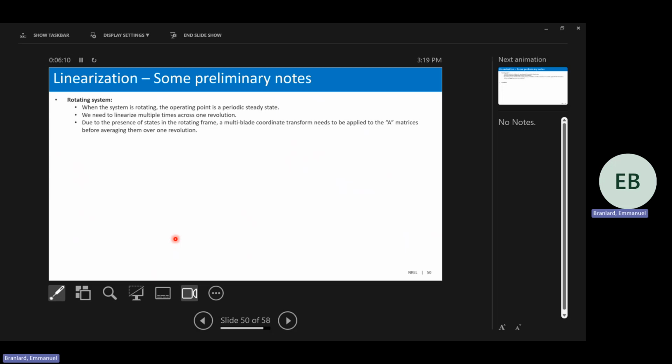One thing to note is that our systems are usually periodic, which we are kind of removing at the moment a bit, but I think the true reason is that we have states that are in the rotating frame of reference. So for the blade elastodynamic degrees of freedom, if you had only one flapping mode, your blades can flap at different times. Basically, that's what's happening. Because you have 3 blades, they could all flap at the same time, or it could be the first blade flapping, then the second one, and the third one.